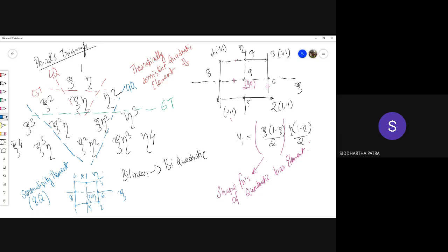Okay, let me say something. First of all, there are certain rules for choosing shape functions. The shape functions should be complete from the lower order to higher order, so that way you only get to skip the highest order. Also, since the element should not be partial to either the xi or eta direction, you cannot skip a non-symmetric term. You should always keep a term that is symmetric in xi and eta, hence xi square eta square, and it is also the highest order term.